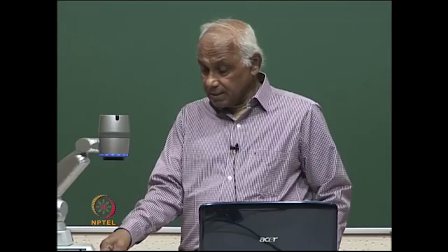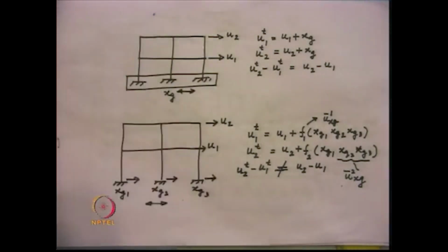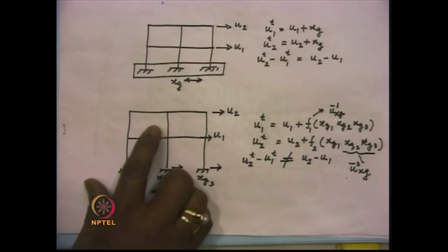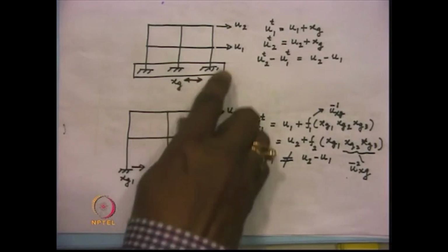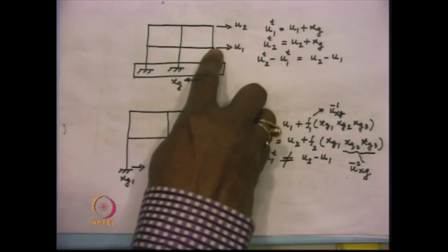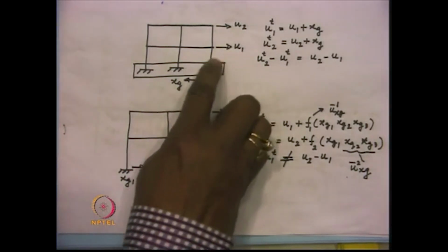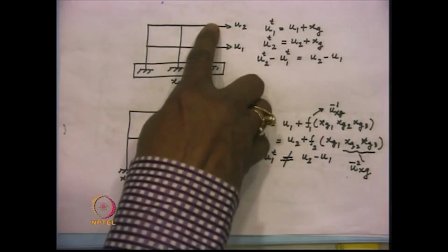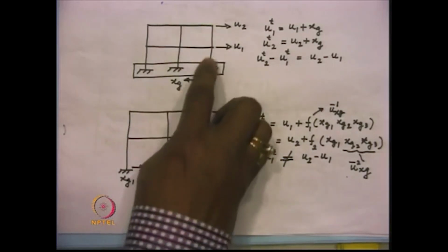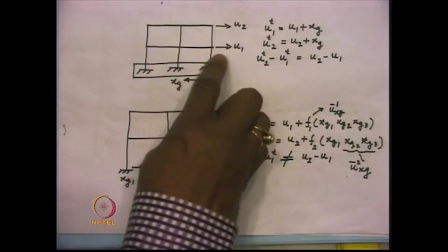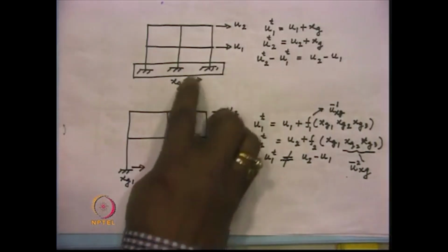And for that, let us take these two figures. In the first figure, all the supports are undergoing the same displacement. As a result of that, the quasi-static displacement at this point and at this point will be same as xg. The relative displacement of these 2 points with respect to the support will be caused by the time varying inertia force, and therefore, at every instant of time t, we will have a relative displacement u1 at this point and u2 at this point.